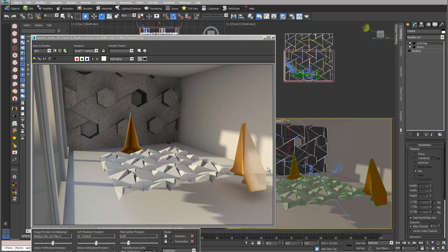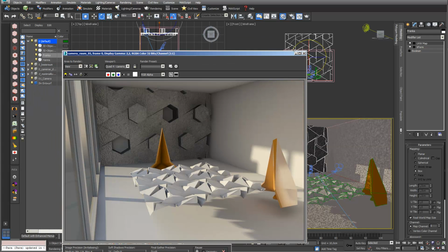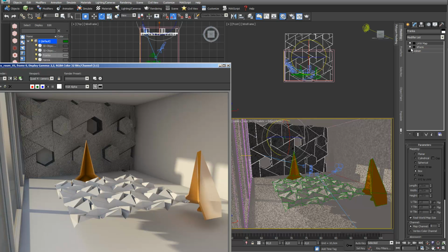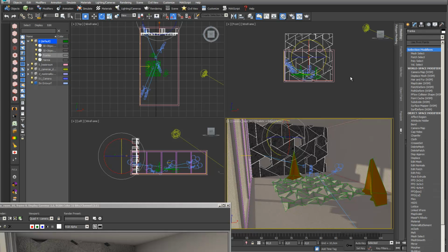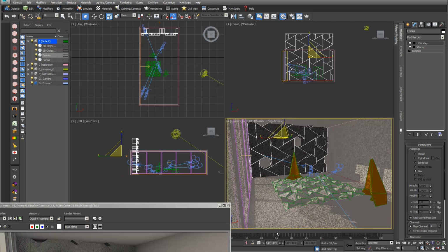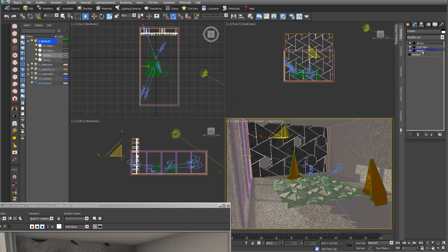The result doesn't look too bad, but the back looks really weird. It was just one material, and this material looks too big, and what was missing actually was this X form again, because I scaled it, but this X form was from another scaling for my pattern to 30 centimeters. So if I select it and go into scale, we can see it's again the scale of 1461. And if I choose this object and say reset X form again, then we see what's happening.